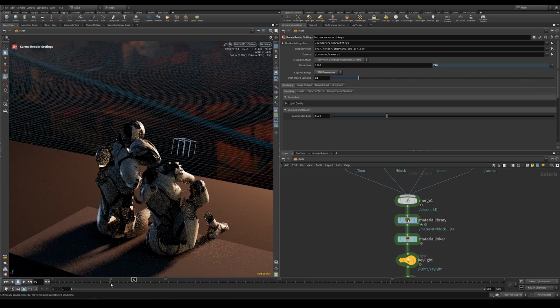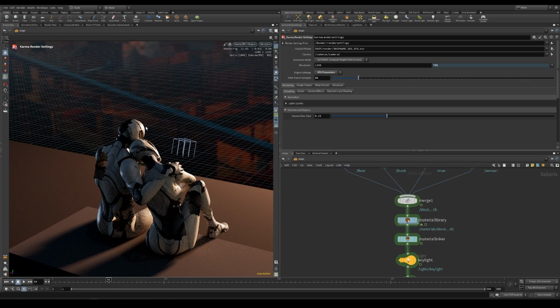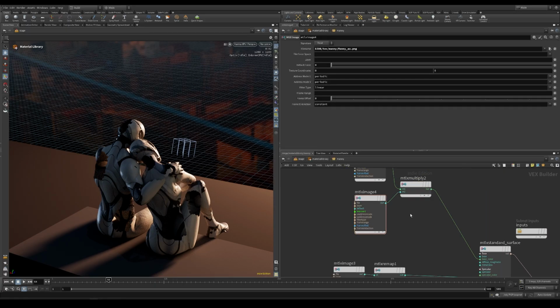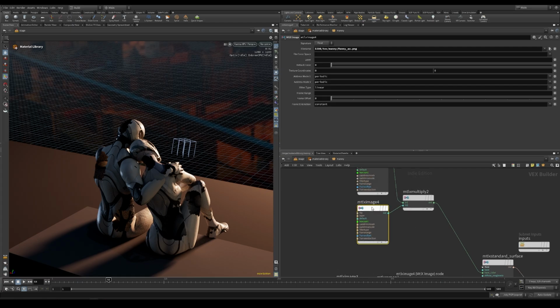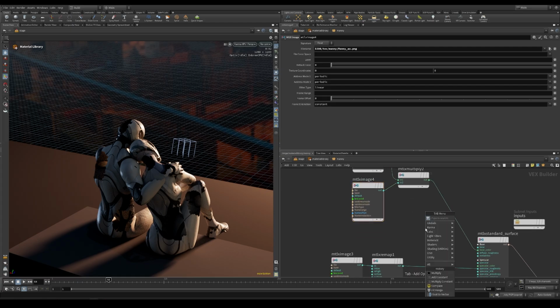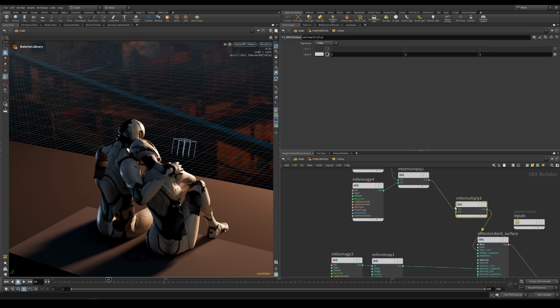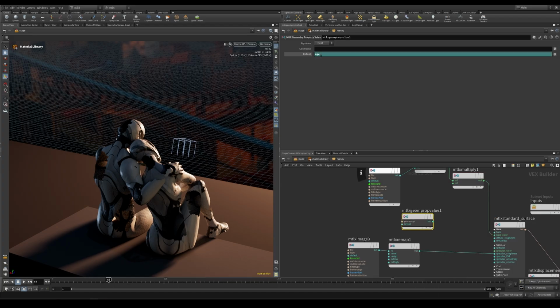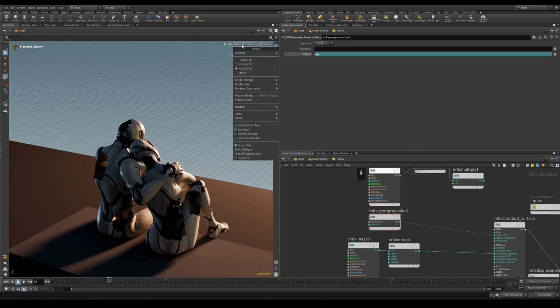And I want to do a slight modification on the material. I want to use the edge map to drive a little bit of darker value around the edge. So if I go in the material of the man, here we have the base color, which currently is being multiplied with some ambient occlusion texture already. We also want to multiply it for the edge map we have, and we can retrieve it with the geometry property value. It was called edge, and it's a float value. And let's plug it to the base color, let's see what happens.